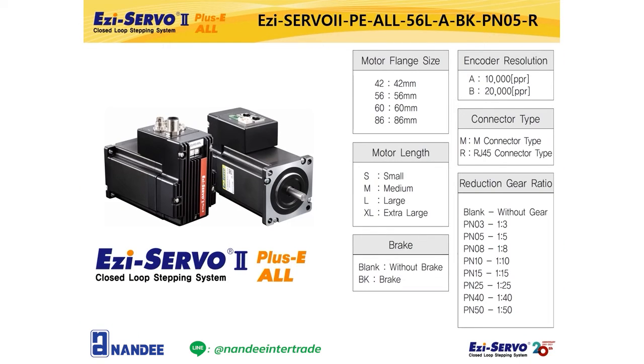First of all, I will explain the combination model name of Easy Servo 2 plus E-All product. In the example model name, PE means Embedded Controller with Ethernet Network, and ALL means an all-in-one product that combines a motor, high-resolution encoder, drive, motion controller and Ethernet network. 56 means 56 mm motor flange size, and L means motor length. 8 means a product with 10,000 ppr encoder applied. BK means that a brake is attached to the motor, and PN05 means that a planetary gearbox is attached to the motor.